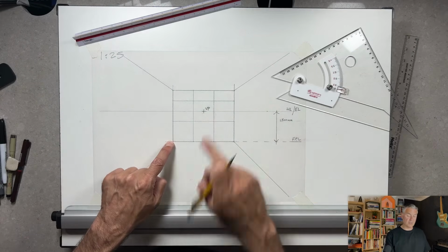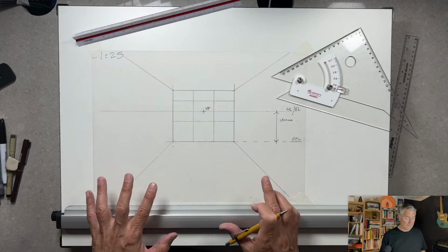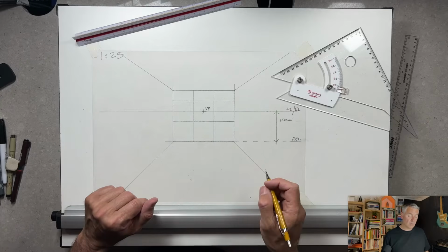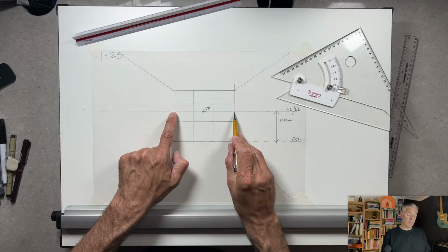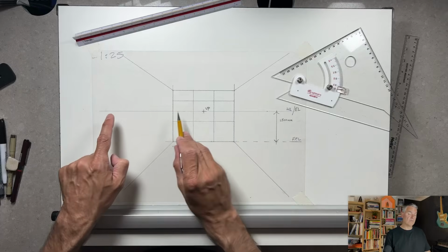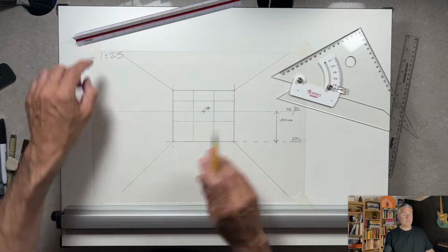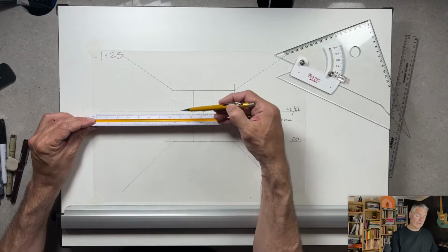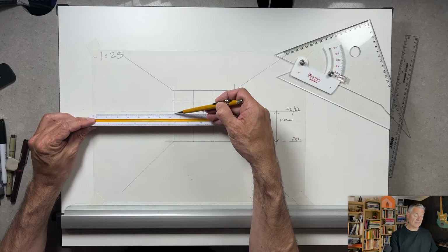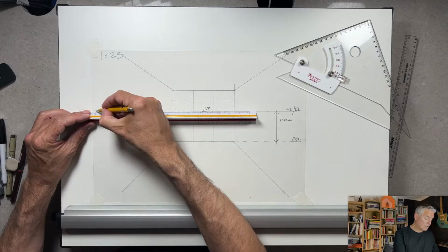I've got my 3 meters by 2.5 meters, and I know I've got 3 meters out from this back wall, but I don't know how to do that yet. So there's another measurement we need to do. We take the width of our wall, 3 meters, and add 25% to that, which gives you 3750 millimeters. Then we move that dimension out from the edge of our wall. On our scale rule, that's 3, 5, 6, 7.5, so we can make that mark on the edge.